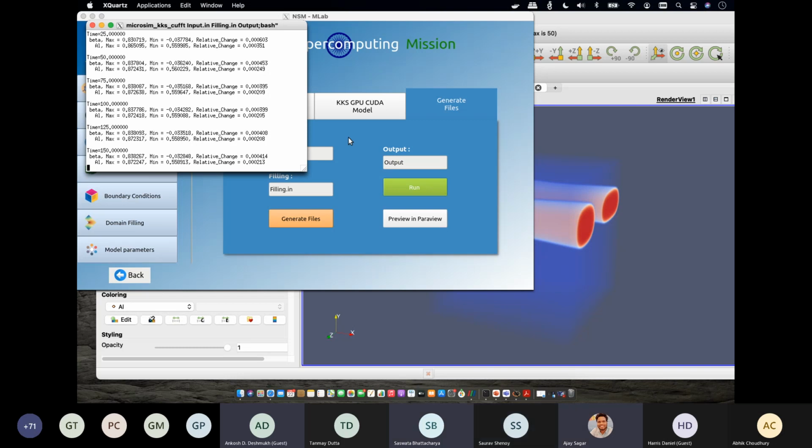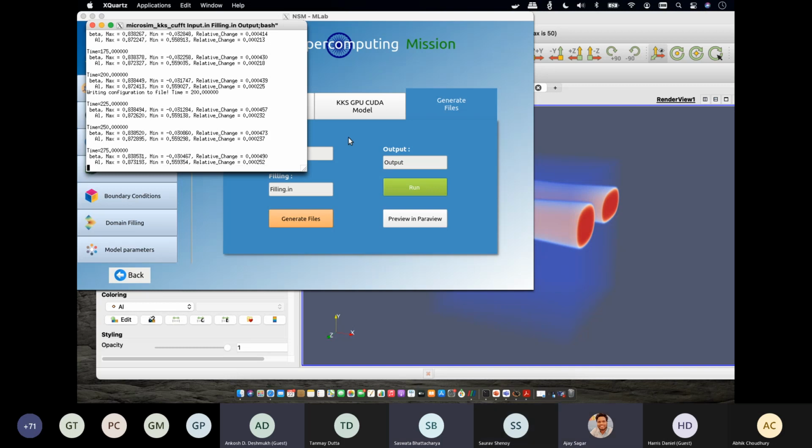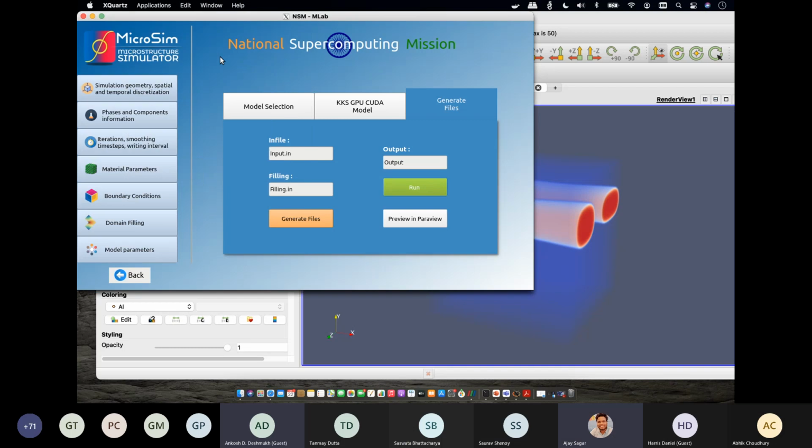Again, here be very careful. One of the important concerns that I found out. See again, if you are running, please note to make sure that your DT, again, it's a semi-implicit method. It's not a fully implicit method. It's not like the open form method that Abhi discussed. So any DT will not work. Please try to understand. So this is another thing that may become unstable. I'm stopping it now.